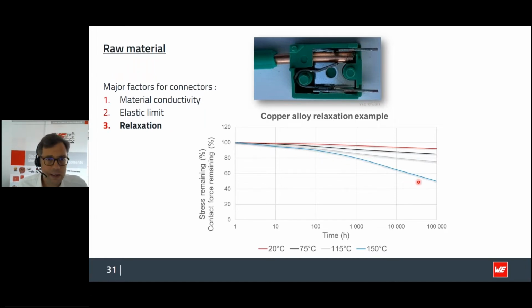It's some kind of stress that you have over the lifetime. In this case, it's shown here. Of course, the temperatures you apply are very high, normally about 150 degrees. You do not find that in many applications, especially due to the fact that FR4 material, which is used for PCBs, also has a limitation up to 150 degrees Celsius.